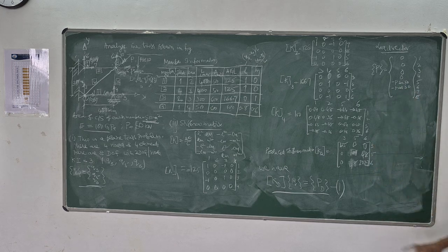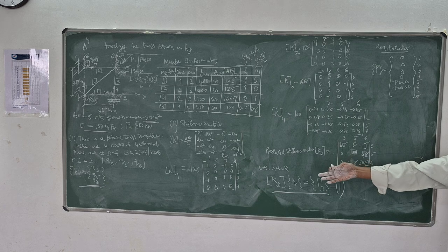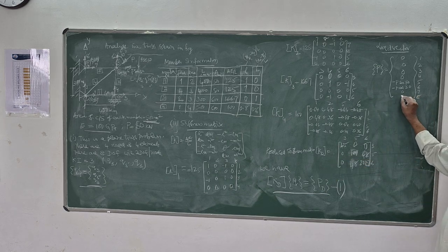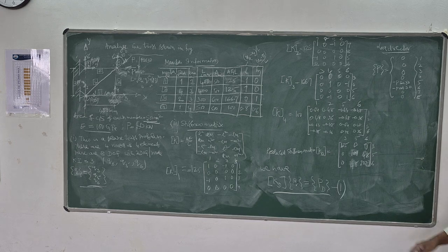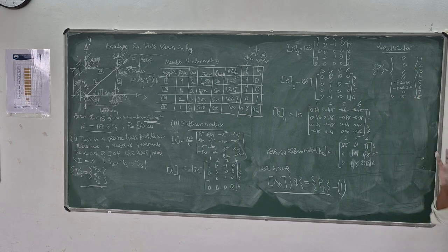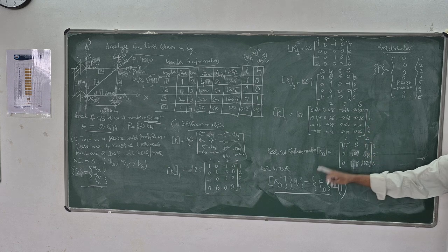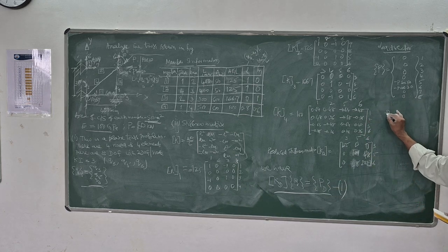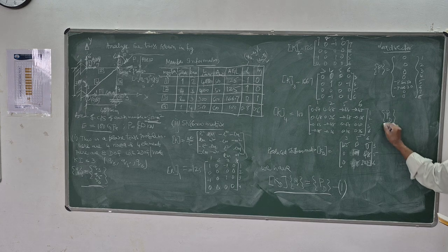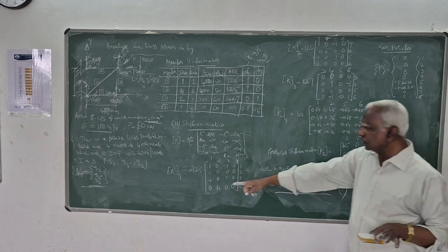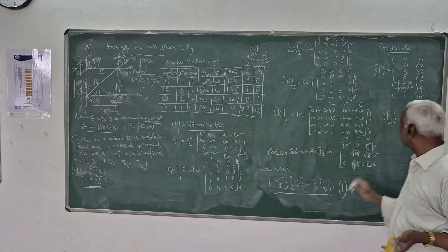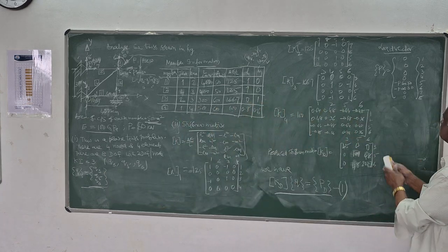P is 50, you can substitute. Or if you have taken newtons, convert 50 to newtons, that's all. 7, 8, no load. So this is how you have to prepare the load vector. Stiffness matrix, load vector. Here you have to take PD corresponding to unknown displacements 3, 5, 6. That is the reduced load vector.